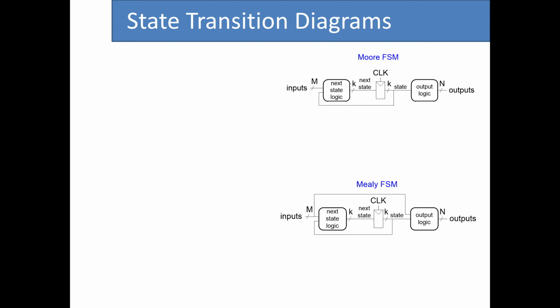So you might say, okay, what is the point of this circuit? The point is that sometimes it is preferred to use a Mealy FSM because we can see the effect of changes faster at the output, even though having this extra path doesn't stop the circuit from still being considered a synchronous sequential logic circuit.